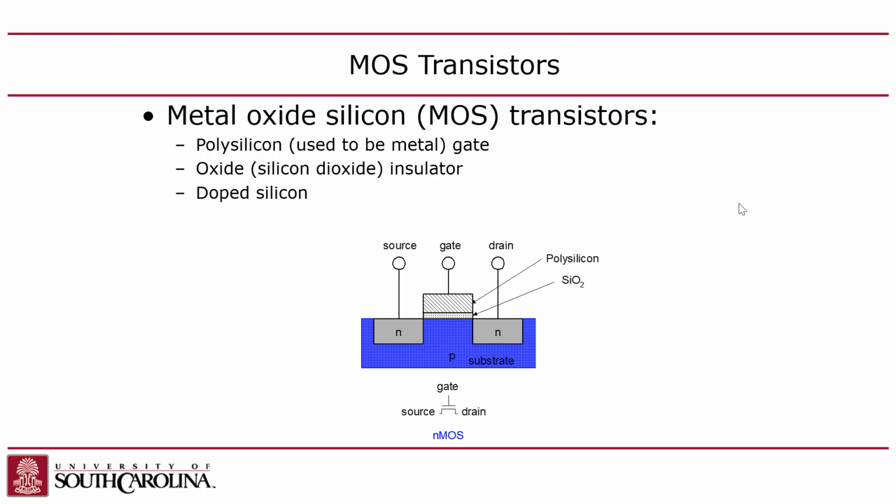But that's not actually what it is, because as I mentioned, they're cheating a little bit. They're making a 3-dimensional channel, I think. They're doing this thing where the modern processes make the channel 3-dimensional. It's called a FinFET. So they've slightly altered the structure here to add another dimension, right? And then they advertise it as having effectively a 7 nanometer channel, right? What's the actual channel size? What's the actual distance in an Intel chip? I don't know. It's probably still 90 nanometers, 45, something like that in reality. You guys with me? Okay, so that's the whole idea.